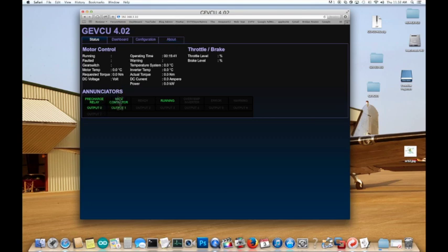And here's our pre-charge relay, our main contactor output we're running. We don't have a lot else because we're not hooked up to a DMOC and getting information from it. But I can show you something here. Let's disconnect the JEVCU and plug it back in, and we should automatically pick it back up when it comes online. And here I am at 8 seconds. I have my pre-charge relay and my output 0 activated, and at 14 seconds the main contactor and output comes on. We can see we're running.